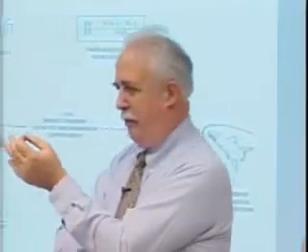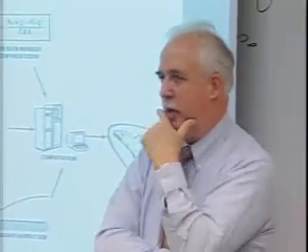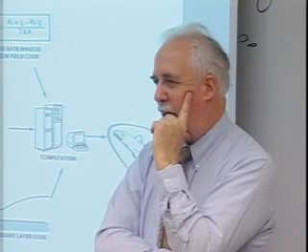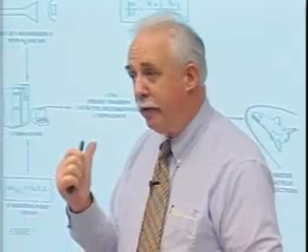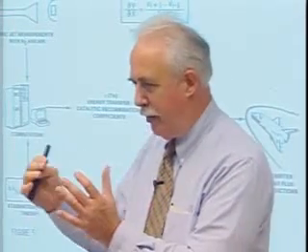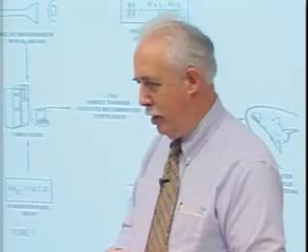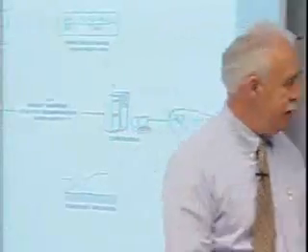The tiles are a very efficient system. They're low weight, they're fragile, but they're very efficient from an energy standpoint. The carbon nose and leading edge are heavy, and they don't insulate worth a darn. I mean, that's a layer of carbon. When it gets hot, it radiates out, but it also radiates in, and so you have to have an insulation behind that. And in fact, the way we're able to reconcile the environment with the temperature capability of the carbon is it's sort of like an oven, and it's easier to illustrate on a leading edge.